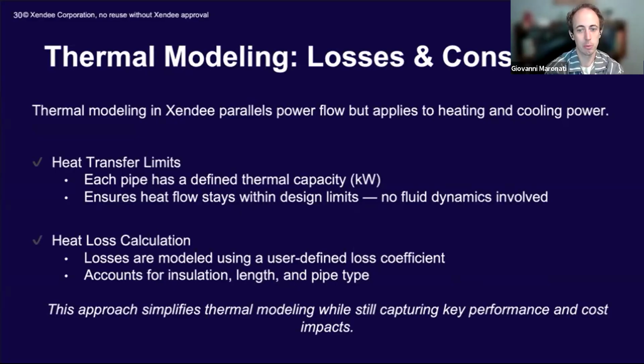So in practice, the optimizer trades off whether to use larger pipes that have better insulation and cost more, but would reduce the thermal losses, or use smaller or poorly insulated pipes that are cheaper but waste energy as energy is transferred between nodes. Again, here multi-node shines because it captures those site-wide interactions, and all of this is included in the optimization.